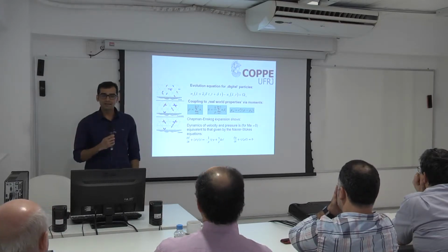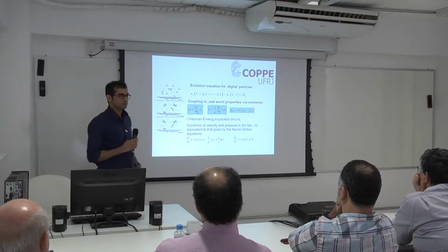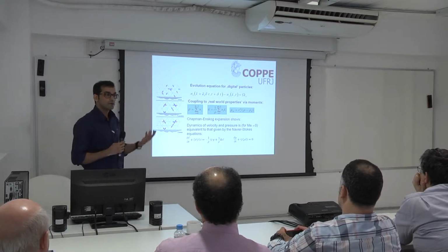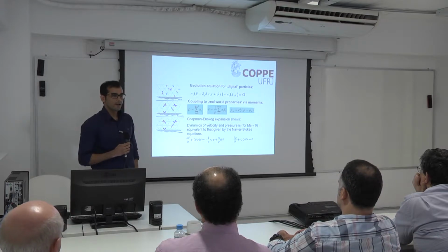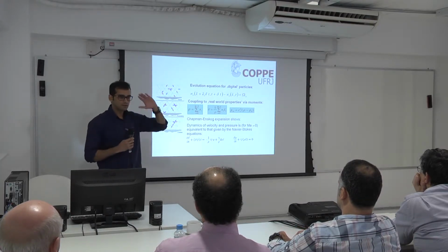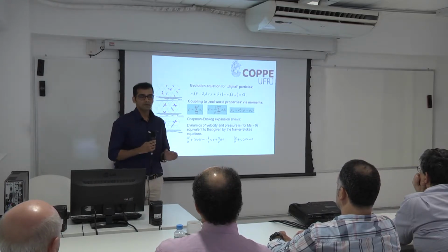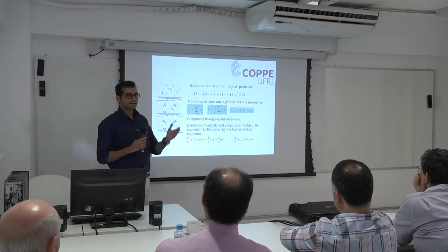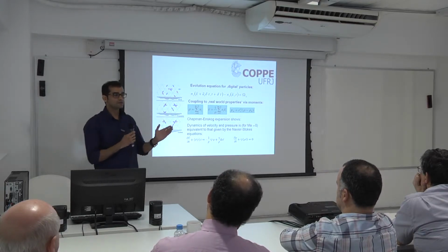We have nonlinear convective terms in there that we cannot ignore. So how do we solve for the pressure? To solve for the pressure, we need the Poisson equation. And if you solve the Poisson equation, your data communication has to be global. That costs a lot, and the computational efficiency goes down. That is a drawback when you go for pore scale modeling and use Navier-Stokes solvers.